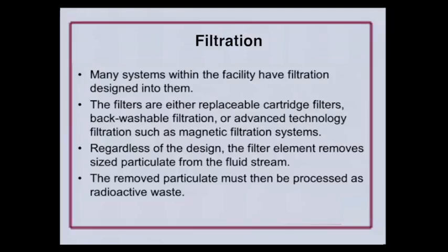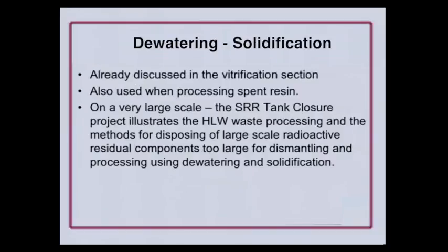Regardless, that removed particulate has to be processed as radioactive waste, whether it's through the removable discarded cartridge filter, the residue from the backwash, or even the magnetic and the backwash that comes off that. Dewatering and solidification is another way of handling liquid, and we've already really discussed that.